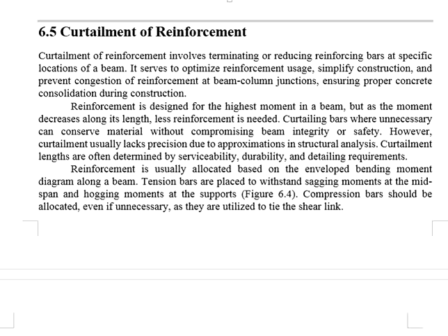Only then can you finalize the arrangements of the reinforcement in the members, taking into consideration the minimum amount of reinforcement bars in this section, at least 1 bar at the corner of the beam section, minimum bar size at least 12 mm diameter, minimum bar spacing, maximum bar spacing, and so on and so forth.